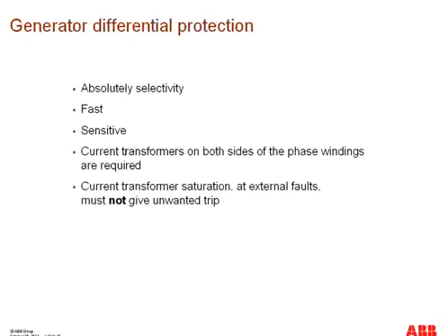Let's talk about now the differential protection itself. As with all other differential protections employed, whether it's a transformer or a line protection, the foremost quality of differential protection is that it is absolutely selective, and the protection zone is defined by the location of the CT.